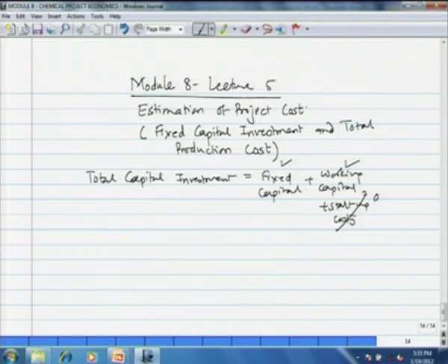There are two types of plant. One plant is a multi-process grassroots plant or a small scale plant or just capacity addition, what is known as battery limit addition. A grassroots plant is defined as a complete plant erected on a new site. The investment for such a plant includes all the costs of land, site development, battery limit facilities and auxiliary facilities.